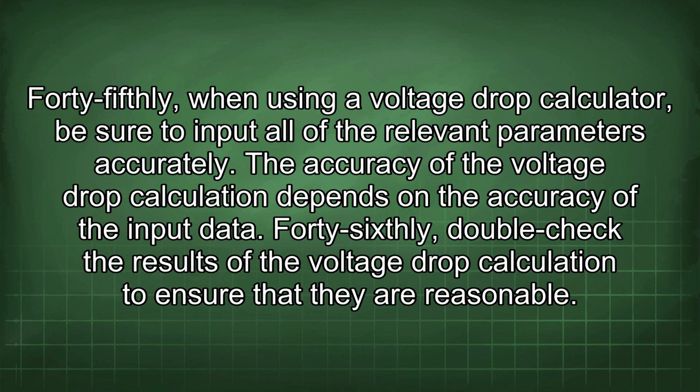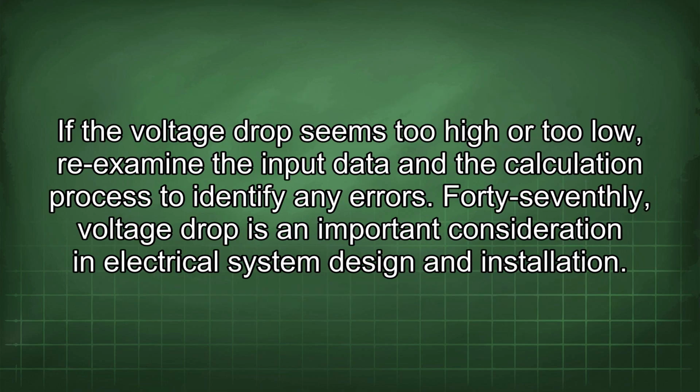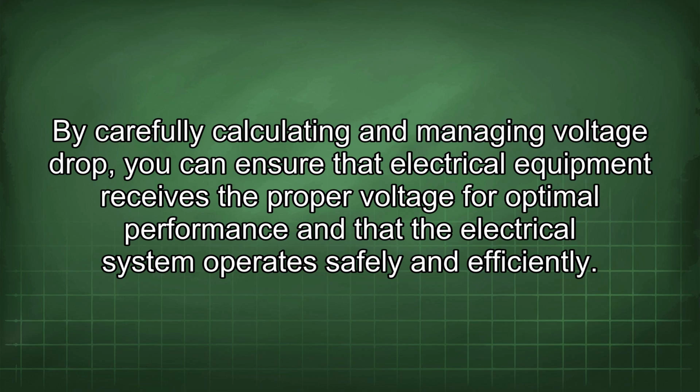46thly, double-check the results of the voltage drop calculation to ensure that they are reasonable. If the voltage drop seems too high or too low, re-examine the input data and the calculation process to identify any errors. 47thly, voltage drop is an important consideration in electrical system design and installation. By carefully calculating and managing voltage drop, you can ensure that electrical equipment receives the proper voltage for optimal performance and that the electrical system operates safely and efficiently.